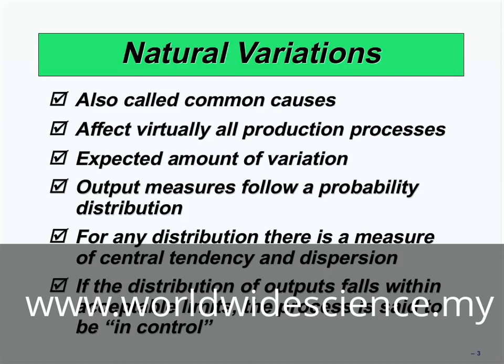They tell you that if the current temperature changes, for example, 2 centigrade up or 2 centigrade down, there is no problem. But if the temperature changes out of this range, something is wrong. You should stop the process and see why the temperature has changed more than this range or lower than this range.